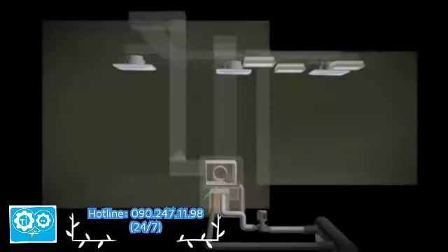For the airflow system, it is operated using an auxiliary fan which creates the air cycle from the room and mixes it with fresh air from the outside to the air handling unit and returns back to the room. The type of fan used is a centrifugal fan, powered by a motor and connected through a belt.